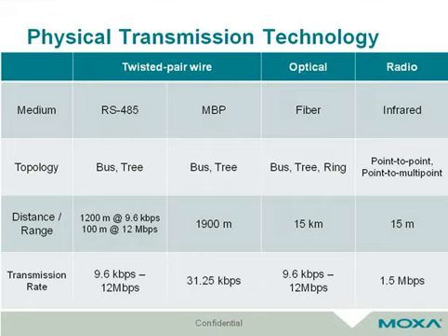MBP, or Manchester Code and Bus Powered, according to IEC 1158-2, is the special physical media used for PROFIBUS PA devices. The PROFIBUS PA device offers a field bus solution for the process industry, which needs bus power.